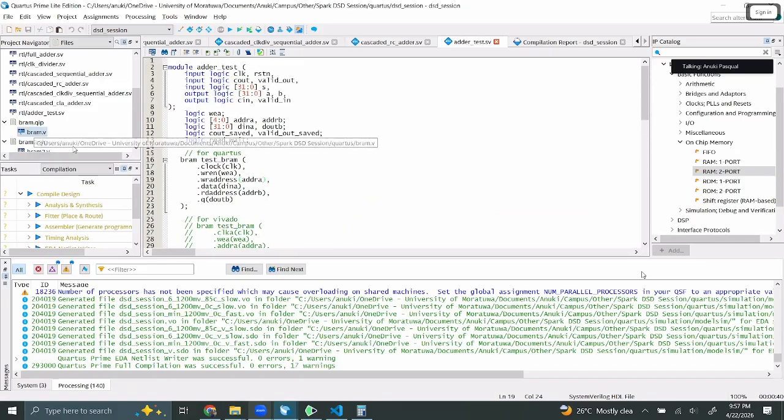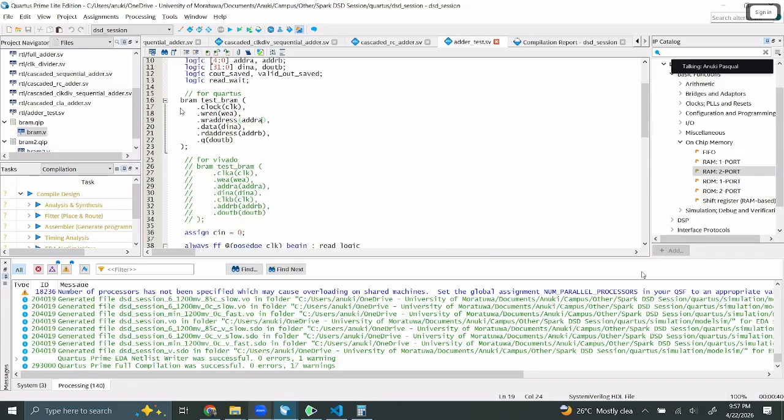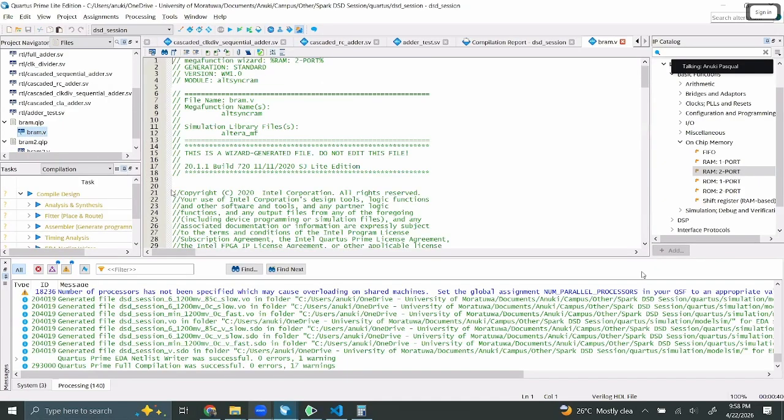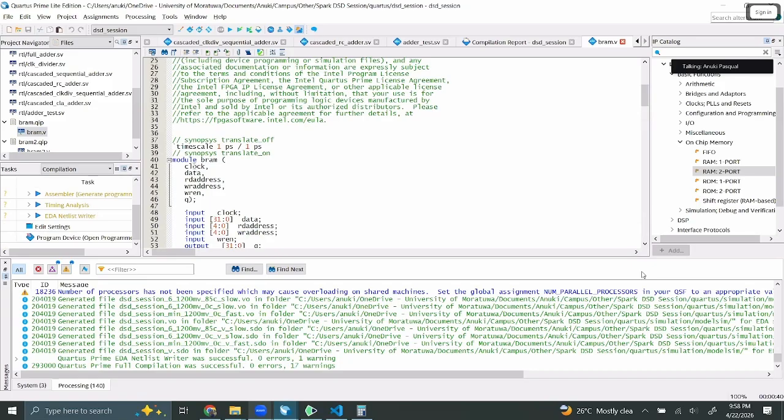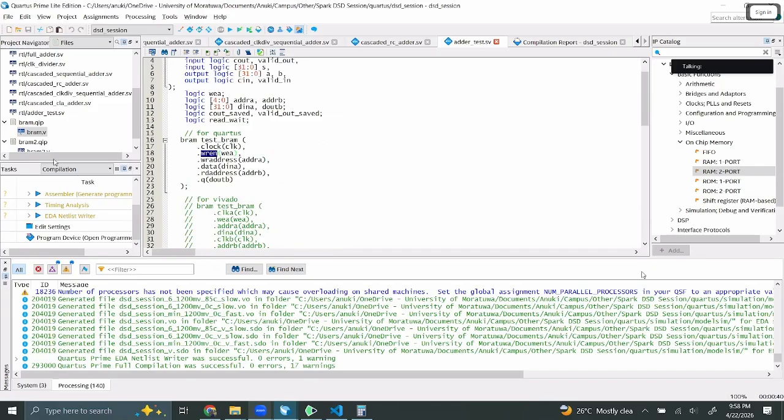The settings of the VRAM might be a bit different in Vivado, but it has the same basic settings as this one. And there also it can be used as a module. The port names and so on can be different between them, so always make sure to check the generated Verilog file to find out the port names. So that's how to make the VRAM. I will show that hex file also.